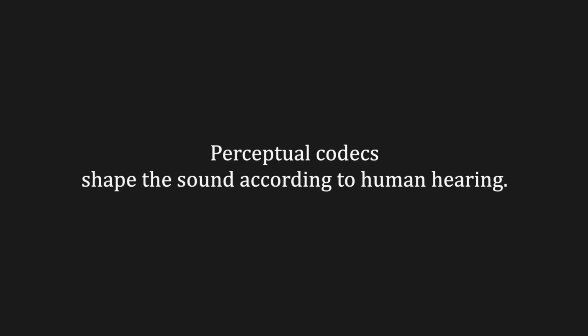Perceptual coding also handles errors better than PCM. In PCM, errors cause wideband noise, but in perceptual codecs, errors are usually confined to narrow frequency bands, sounding like small bursts of low-level noise instead of clicks. These codecs can also apply targeted error correction, giving extra protection to delicate sounds like quiet piano notes while using less for louder ones.